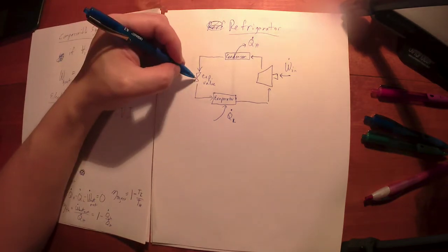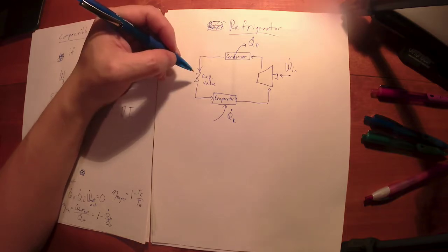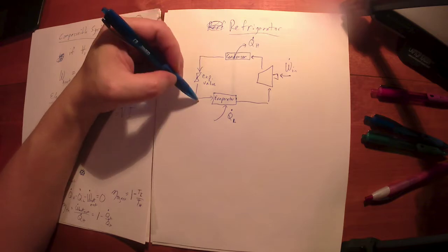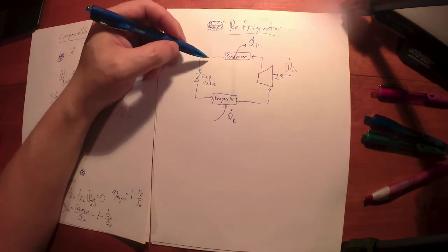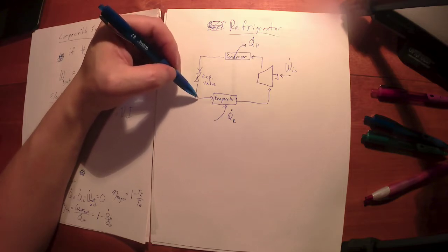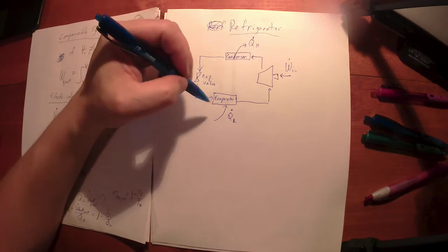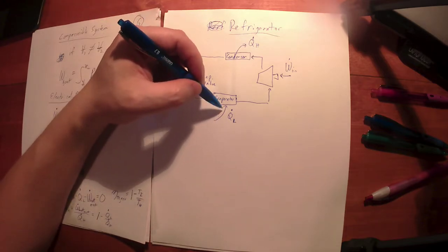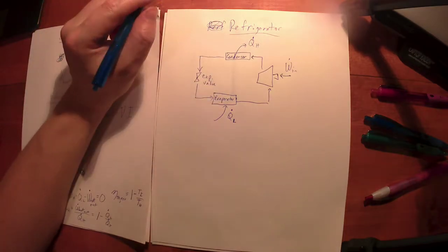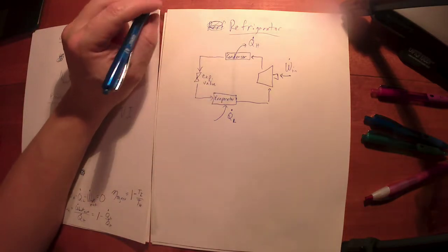Basically, if we can achieve anywhere close to supersonic flow right here at the choke point, magic things happen. And the basic idea is the pressure from here to here will drop, and as the pressure drops, so will the temperature. We get really low pressure or low temperature on this side of the expansion process, and the temperature of the refrigerant is so cold that now it will remove heat, or it'll absorb heat. When we run it through a heat exchanger, it'll absorb heat from the low temperature source.